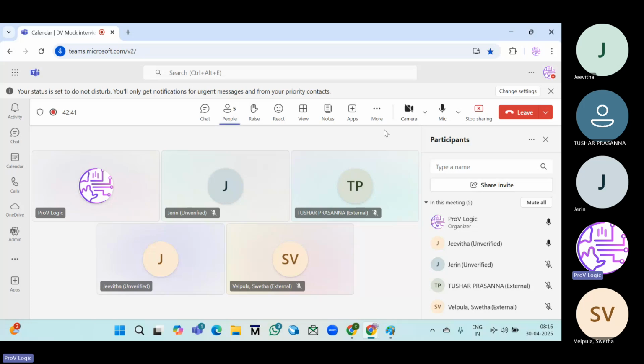I'm just asking about procedural, not whether it is combinational or sequential. LHS side, we have to specify wire. RHS, either it is net data type or reg data type. For which statements? For always? No, that's for continuous assignment statement.